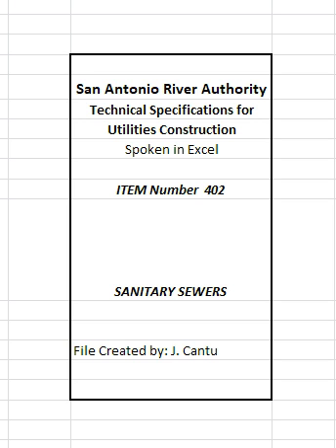Grease interceptors. Gravity. A plumbing appurtenance of not less than 500 gallons, 1,893 L, capacity that is installed in the sanitary drainage system to intercept free-floating fats, oils, and grease from wastewater discharge. Separation is accomplished by gravity during a retention time of not less than 30 minutes. The appurtenance shall be a double compartment, first compartment 60% and the second compartment 40%, with a minimum 20 inch manhole access to each compartment unless otherwise approved by the code official.